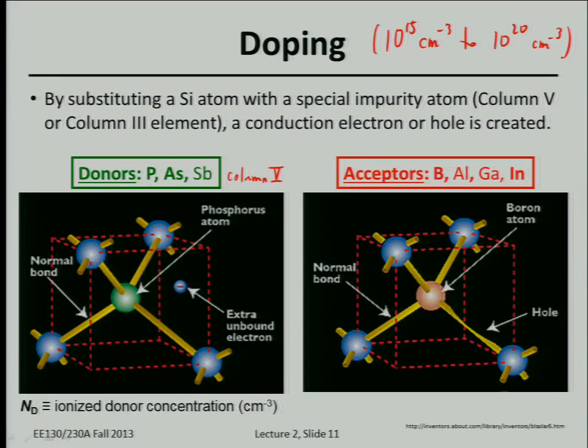Now, if we want, for whatever reason, to have a semiconductor made very electrically conductive, but to have the conduction performed by positively charged holes, we can add an element from column 3 rather than from column 5. Actually, I wanted to ask, you know that model of a person standing up, generating an electron hole pair. Following that analogy, what would be a good model for a donor atom?